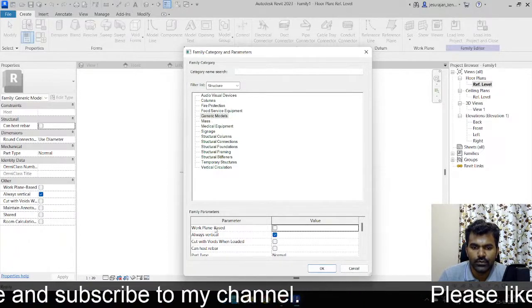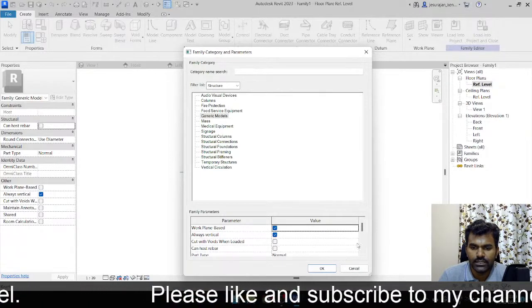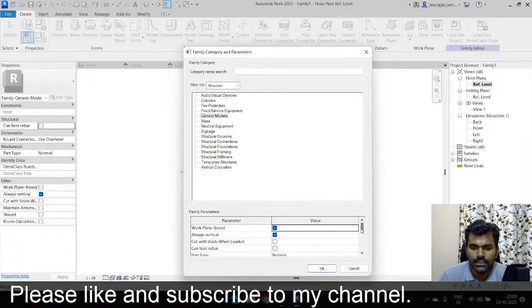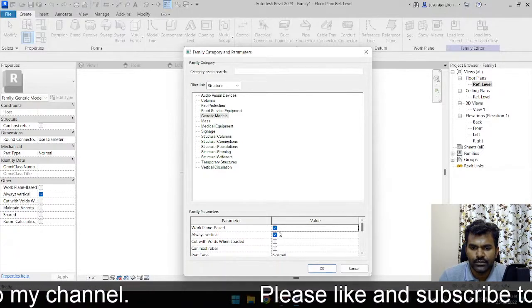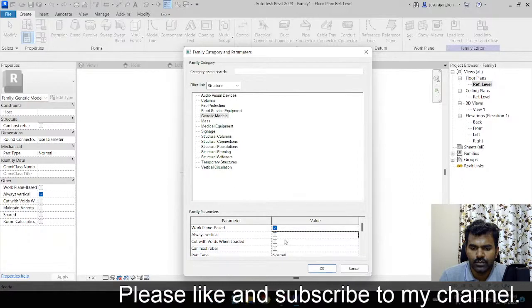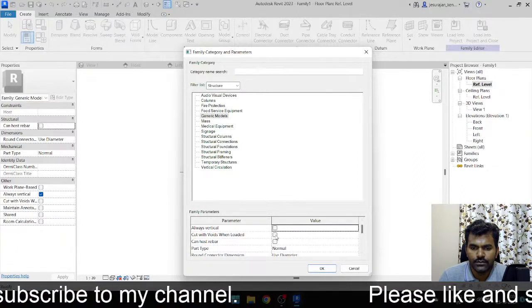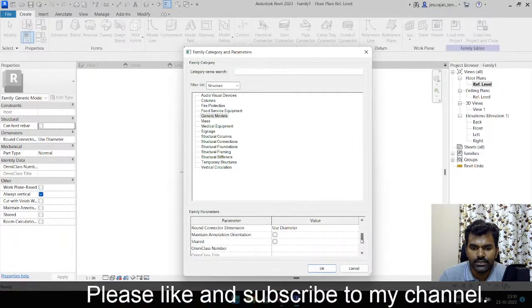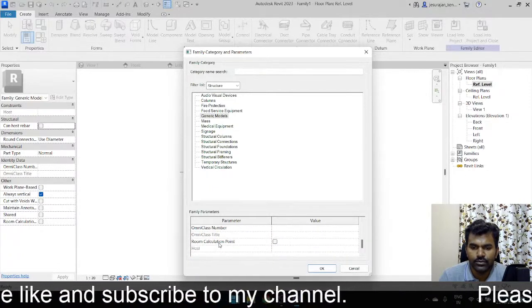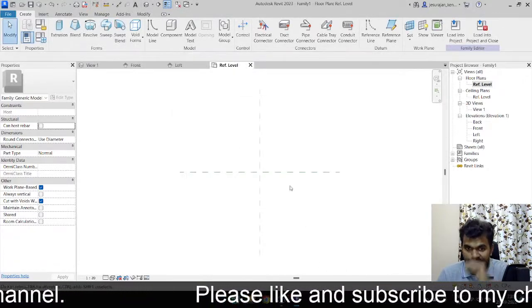And check work plane based, always vertical. I think you can keep it on, no problem. Otherwise you can just uncheck, no problem. And then cut with void when loaded should be checked, and keep it as shared. Maybe you don't have to keep it as shared. Okay, nice.